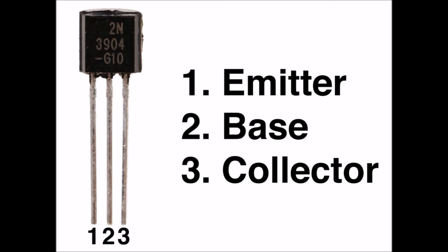Characteristics of transistors from a random website. An important characteristic of a transistor is its beta, or current amplification factor, which is expressed as hFE, static forward current transfer ratio, or hfe, small signal forward current transfer ratio. Both relate to the grounded emitter configuration.